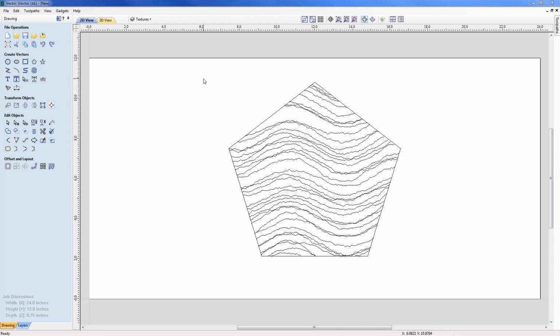Really, there's two different ways. One is to make sure I create a tileable texture in the first place, so each single panel can be basically matched side by side, top and bottom, in order to create a completed texture on the wall. Or the other one is to create the large scale texture in its entirety, in other words full size if it was going to be on the wall, and then use the toolpath tiling to divide that up into separate pieces that would then bring it together. But in this case we're going to make sure we create a tileable texture.